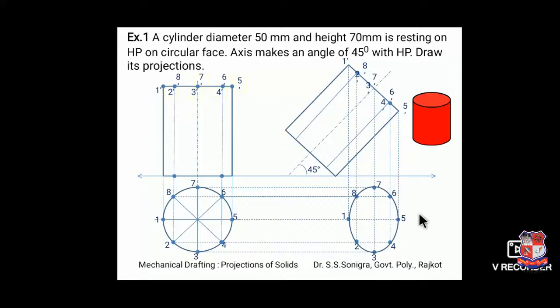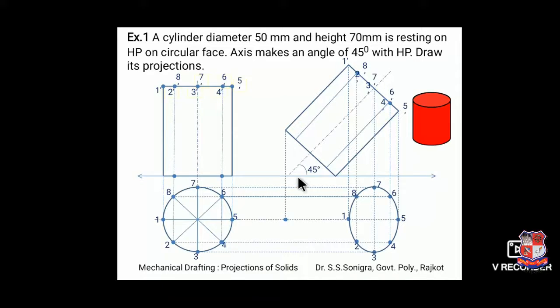here. Now similarly, locate position of this bottom 8 points by drawing respective projections, vertical lines from all these points and horizontal line from respective points like this, and join all these points with dotted line, because this bottom circular face will not be visible from top. If we are looking from top, this bottom circular face will not be visible, that is circular base, that is not visible. So we have to join all these points with a smooth curve, and these end generators to be